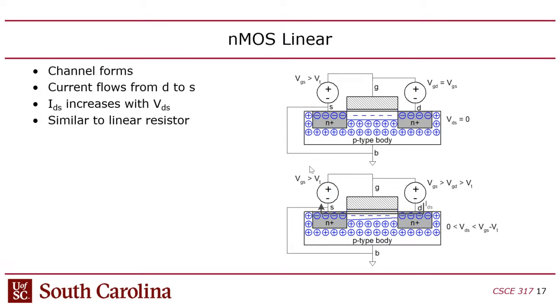Of course, you can change that by changing the doping and I think the oxide thickness. There are ways that you can change that, but generally speaking, it's remained pretty consistent in most modern processes around 0.7. Which is why, if you look at your motherboard settings, you'll notice that you can't really drop the voltage, because modern motherboards have dynamic voltage scaling.